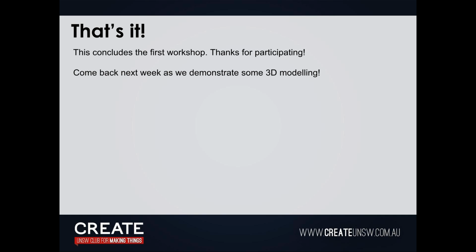When you do this in Rhino, you will probably have to join this whole curve as one single line. If you don't do that, Rhino will cut one section and then jump, unless you do something called vector optimization, where the laser cutter calculates the best way to cut this out. If you don't do that, or if you don't join the lines, the laser cutter will just be all over the place and you'll waste time laser cutting. This applies especially if you're making a large batch of models.